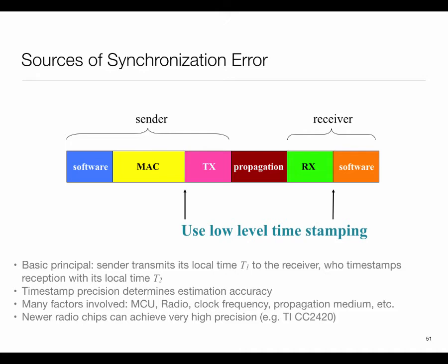Okay, in fact, processors which can work without disabling the interrupt, operating systems and software which do not ever disable the interrupt are tricky, okay, because you have issues of nested interrupts and things like that and all, okay. So that's the other. So there are two sources of problem. One is interrupt may be disabled, and the other is, in any case, if it was not disabled, some initial work has to be done whose delay you need to kind of characterize, okay. So this approach still has some lingering uncertainty.